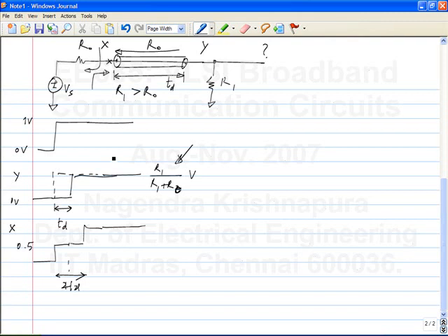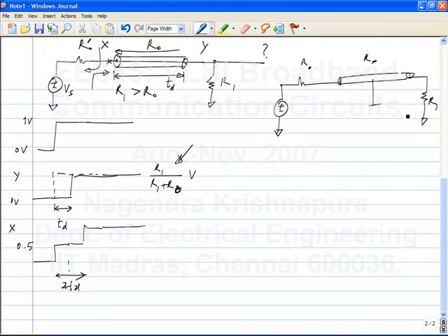So, in this case, if one side is perfectly terminated, what you get will be a delay. So, what happens if this is now different? This is R0 prime, yeah? Input impedance of the transmission line. The characteristic impedance is R0. The question is, this is terminated by R1. The input impedance is something different from R0. Does everyone agree with that? So the question is, why did I write half a volt here? Is half a volt correct or not?